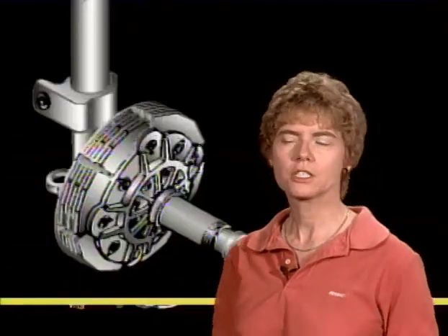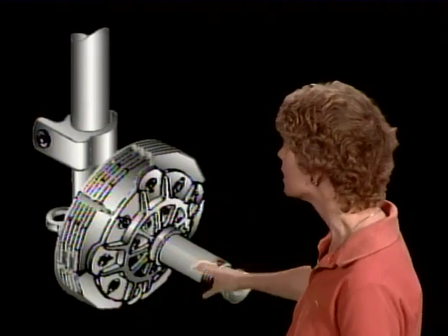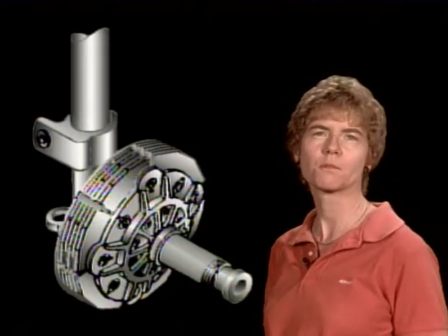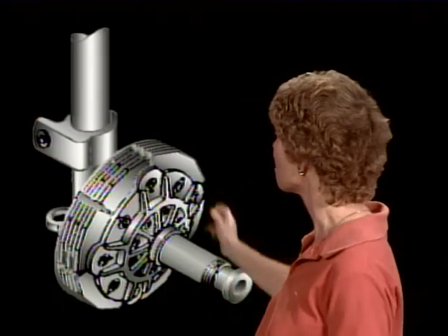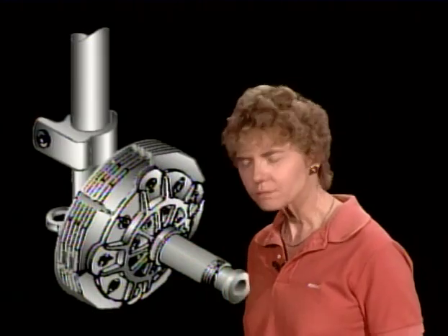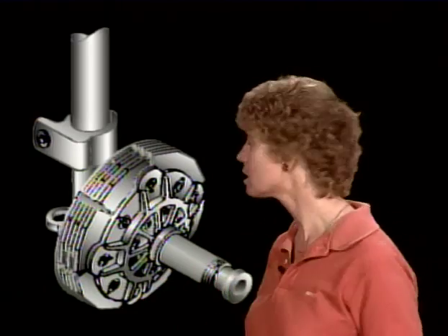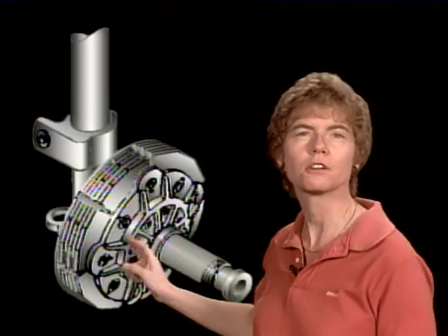Now, as aircraft get larger, typically you'll find them equipped with multiple disc brakes. Multiple disc brakes look very similar to the single disc brakes, except they've got a lot more of those rotating discs. Now, if you've got an aircraft that has multiple disc brakes, and the pilot reports that he's got sluggish and jerky brake operations, one of the things that you need to do is to disassemble and clean the automatic adjuster on those brakes. Now, what's the automatic adjuster?